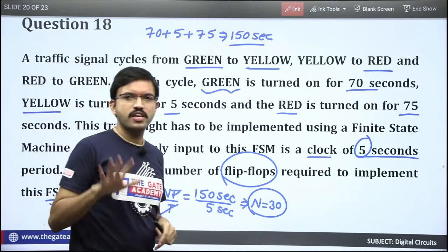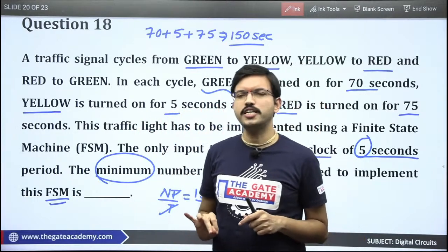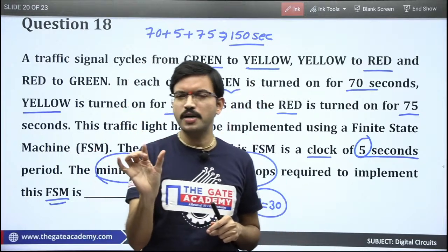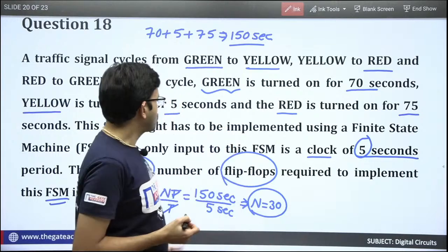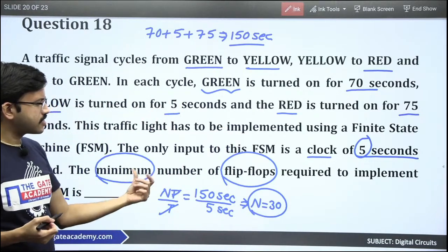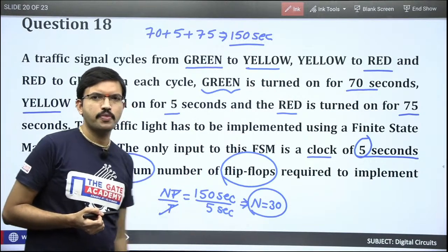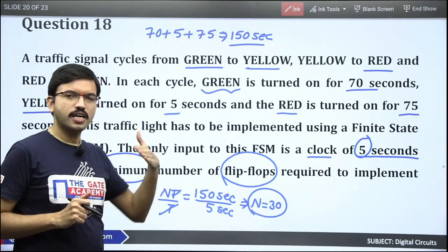have to choose. If you recollect ring counter, Johnson counter and asynchronous counter, among those obviously the number of T flip-flops will give the minimum number, right? So whenever they specify like this, obviously you can take T flip-flops only. Okay. If you are considering D flip-flops, always the number will be more only when compared to T flip-flops.